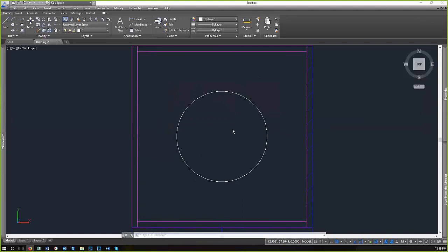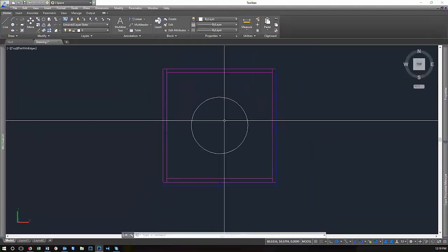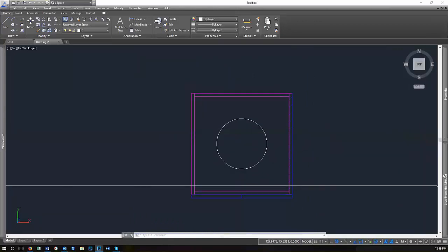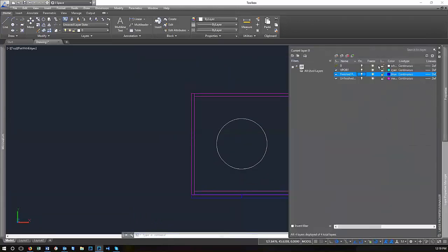So you can group objects by their location or function or any other property that you want the layers to depict in your drawings. So they'll come in with the different colors, and our plot styles that we are going to introduce later also use those colors to show what line weight they're going to use when they're plotted.